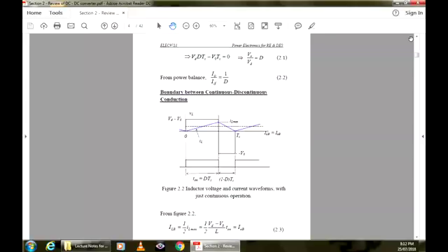In the previous set of slides, I showed a pulse width modulator, PI controllers, a voltage regulator and so on. In those PI controllers, at least for the converter, we are dealing with a constant gain situation. How do we define it? If this is output and this is D, delta V over delta D is the gain. Output voltage rises linearly with D. So if you take a slope, the slope is constant, so the converter has constant gain. That's what it means. Now, that is not always the case.